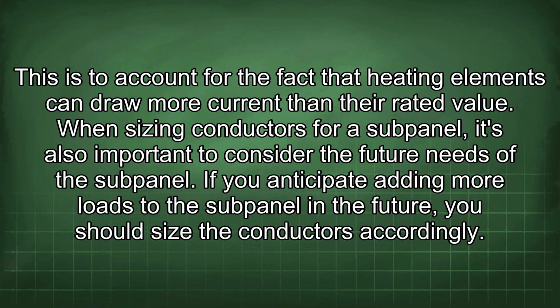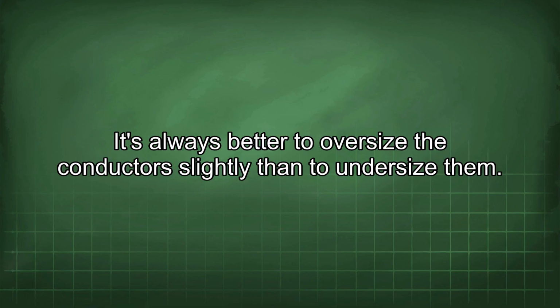When sizing conductors for a subpanel, it's also important to consider the future needs of the subpanel. If you anticipate adding more loads to the subpanel in the future, you should size the conductors accordingly. It's always better to oversize the conductors slightly than to undersize them.